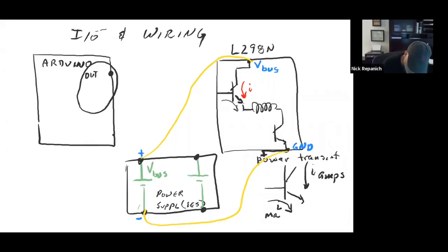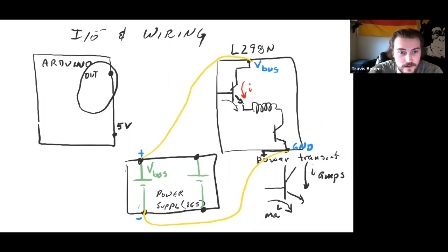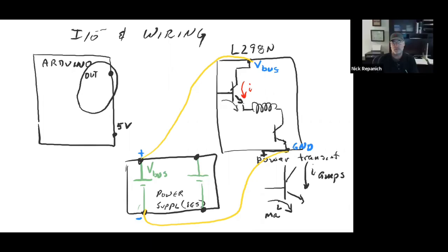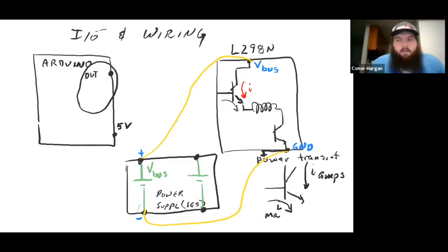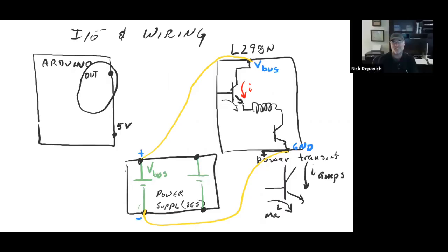Probably there's some pin here that says 5 volts. Okay, what's the first thing that should occur to you when it says 5 volts? You need 5 volts to run that microcontroller? Oh, is that your assumption? Maybe. What's the other assumption that somebody could easily make? The outputs are going to output 5 volts. Yeah, that's the question. That's 5 volts. Is it in or out?